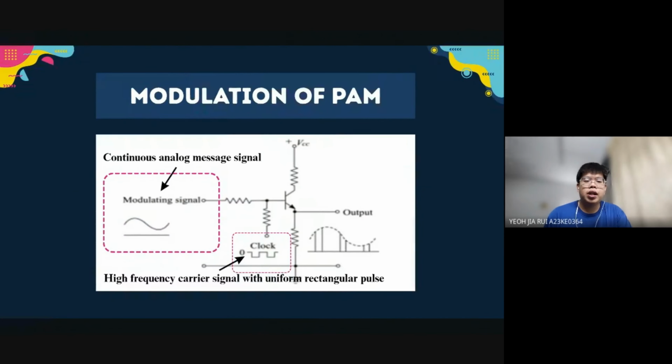Now, how do we actually create these pulses? We start with two main signals: our analog message, like our own voice, and a pulse generator. These signals go into a modulator circuit where the sampling happens. The pulse generator acts like a clock, telling the circuit exactly when to measure the signal. If you are using the standard flat-top method, the circuit takes a snapshot of the voltage and holds it steady for each pulse. The result is a sequence of pulses that stay the same width but change their height to follow the message.